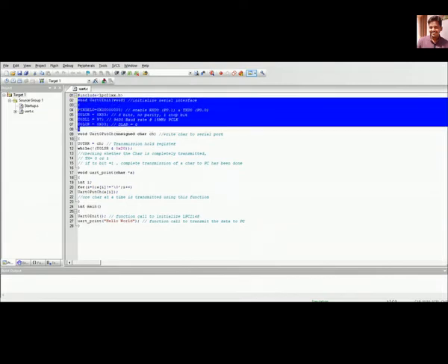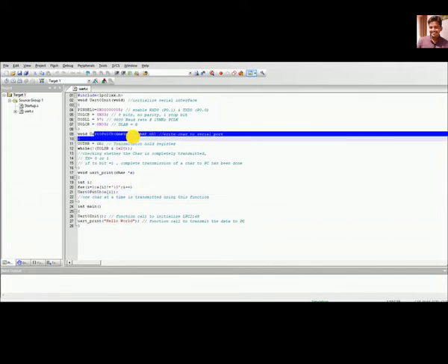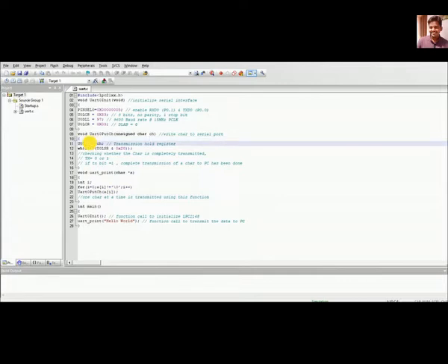Then after initialization, we are going to call the print function. So this is the string that I am going to display. So this will call the print. Okay, and whatever the string is stored in this particular array A, for each character I'm going to send put char. So this is the put char function. So for each character I'm going to store that into the U0 THR register, and then I'm going to use